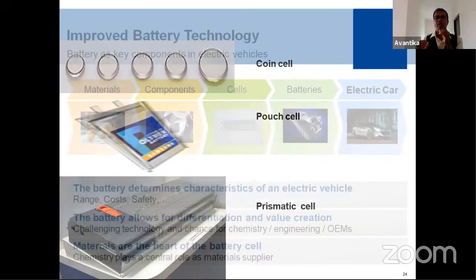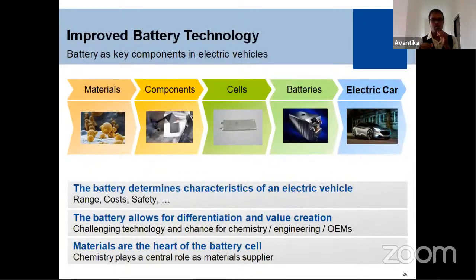So now I am going into details of how one can optimize the cathode materials. Okay, so this is a scenario of the total picture. So right from the start, we have to optimize the material. This is really challenging. So here you can see that most of the materials we have to prepare in that monodispersed particle. I can say in simple terms monodispersed particles. So it is very, very tough to prepare this kind of monodispersed particles.